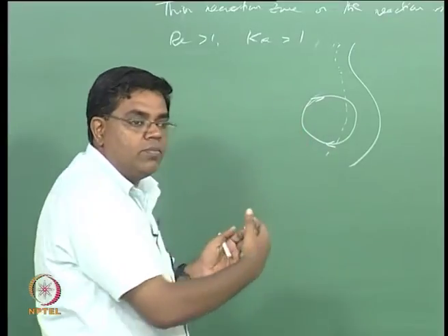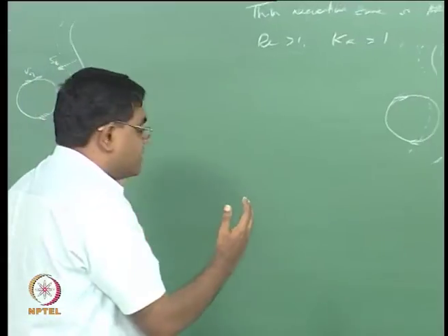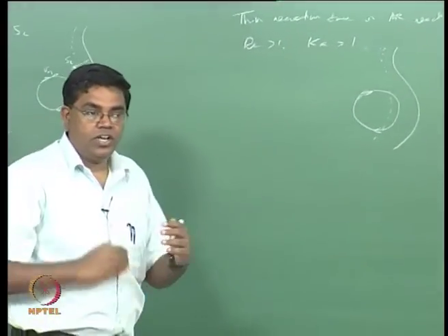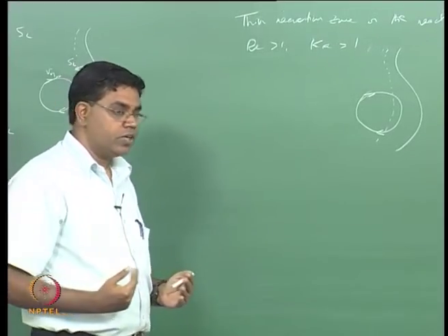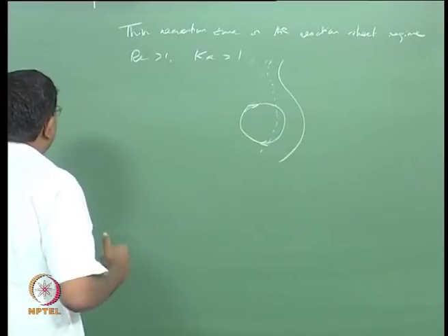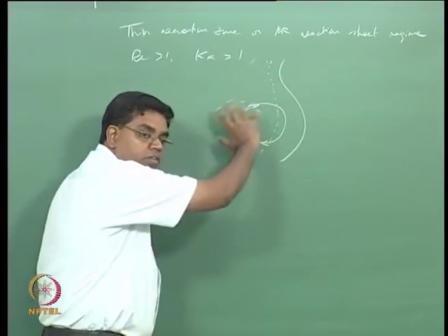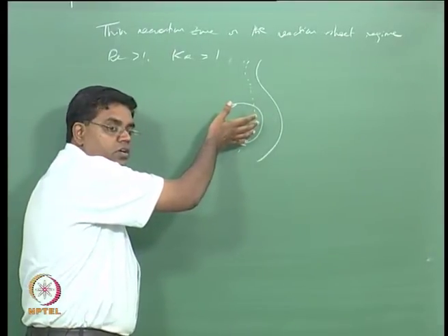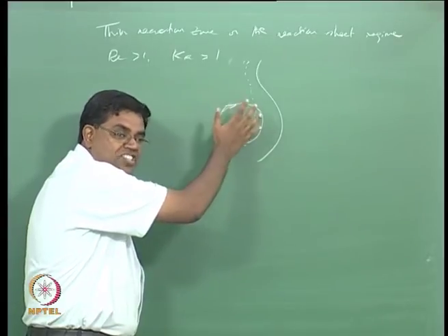So if you want to think about this in a statistical manner, it's as if you had a fairly thick preheat zone. The eddy was doing the job of thickening the preheat zone, right. So you can now only talk about a reaction zone that is trying to accommodate the eddy, but the preheat zone has been breached.